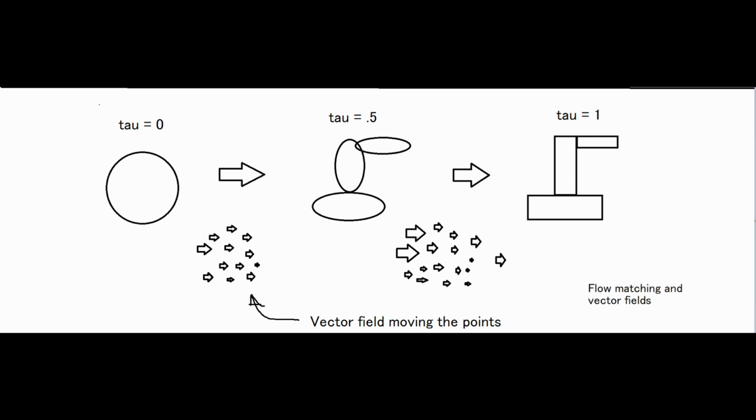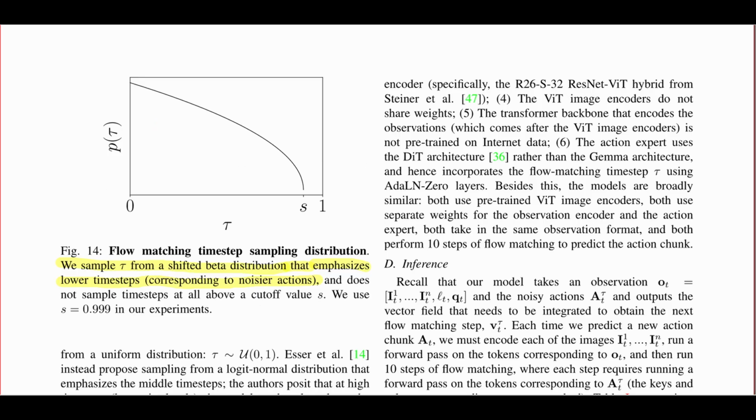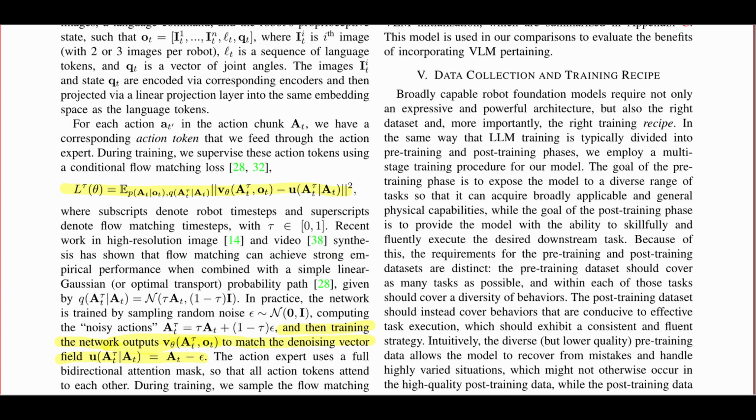So for our case here in Pi.0, the action expert here outputs a vector field, which is the flow at the time step tau. For the untrained Pi.0, this is just going to output complete garbage. So to actually train the model to be a vector field is just to simply regress the predicted vector field onto the reference vector field, which is obtained by interpolating the ground truth action chunk with the Gaussian noise distribution. To me, this is pretty amazing as it turns generative modeling into just a regression problem, and I find that simplicity to be pretty beautiful.